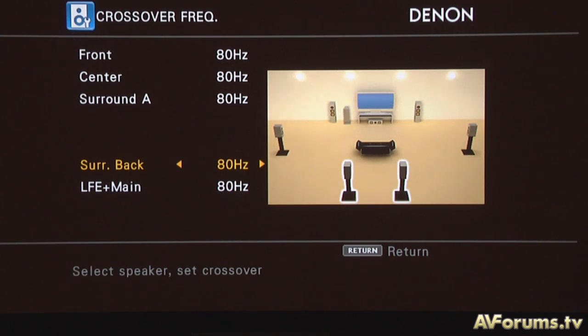The reason why we redirect the bass below 80 Hz is that that frequency is quite a low frequency, and it puts quite a lot of strain on our main speakers to try and recreate that. It's much more efficient for that to be sent to a separately powered subwoofer, which has a large driver and can create those frequencies much more easily. The second thing is that at those low frequencies, the subwoofer should be omnidirectional. Omnidirectional just means that the sound comes out in all directions, and that means that we shouldn't be able to locate the subwoofer in the listening room.